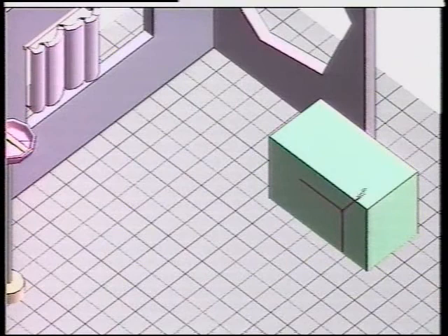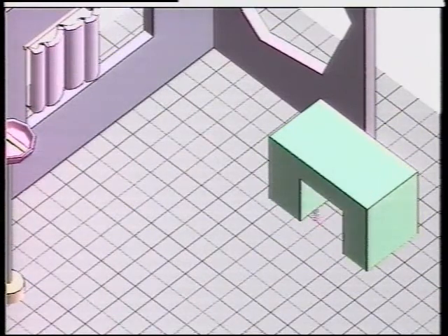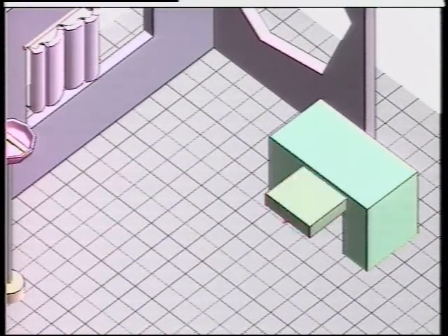Next, we subtract a drawer from the desk and draw a single line. Since we drag parallel to this line, it becomes a single-axis translation constraint. Dragging perpendicularly to this line would have yielded a rotation constraint. Constraints in Sketch are limited to tree-like hierarchies and persist until they are overwritten by a different constraint.